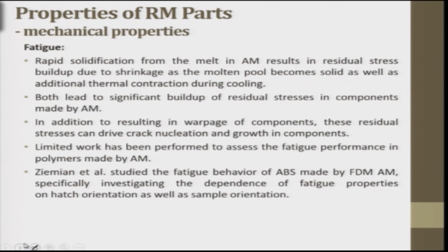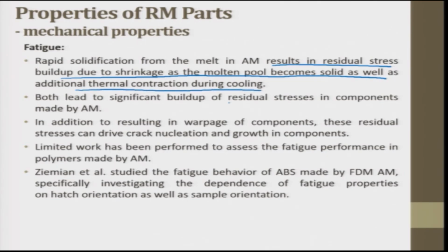Next is fatigue. Rapid solidification from the melt in additive manufacturing results in residual stress buildup due to shrinkage as the molten pool becomes solid, as well as additional thermal contraction during cooling. Both lead to significant buildup of residual stresses in components made by additive manufacturing. In addition to resulting in warpage of components, these residual stresses can drive crack nucleation and growth in components.